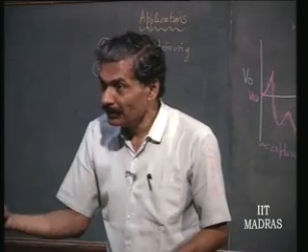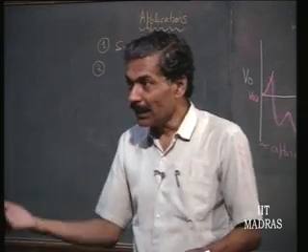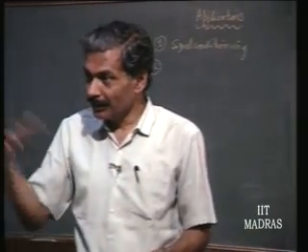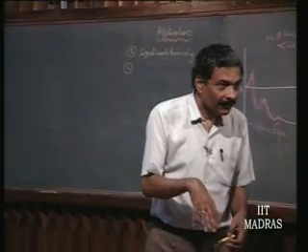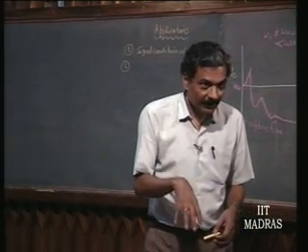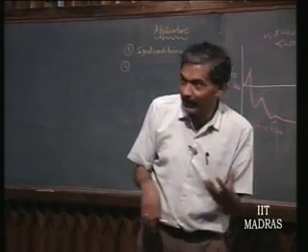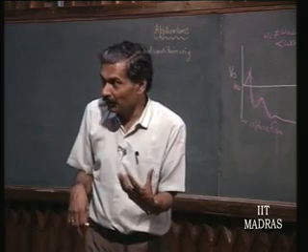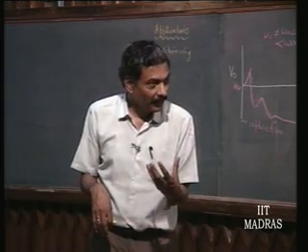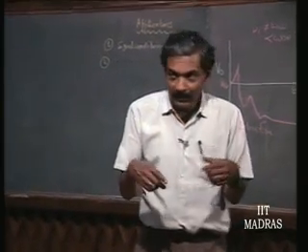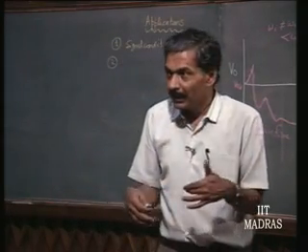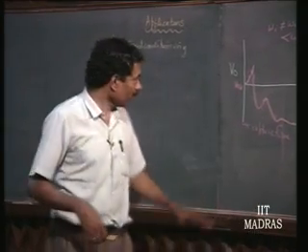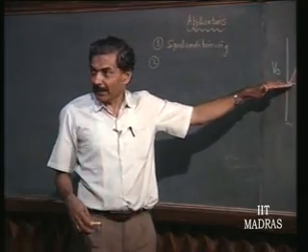So, you will have two PLLs functioning, one at horizontal synchronization frequency, another at vertical synchronization frequency, getting the composite video at the input. So, whenever you have the wanted information of horizontal frequency, the output is going to correct itself to the correct DC.